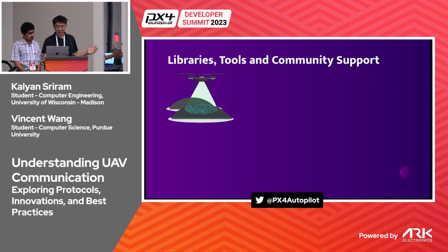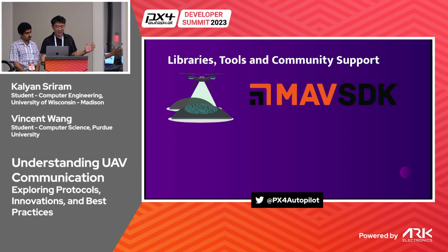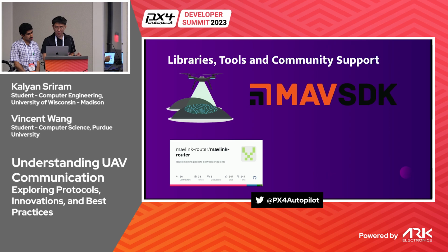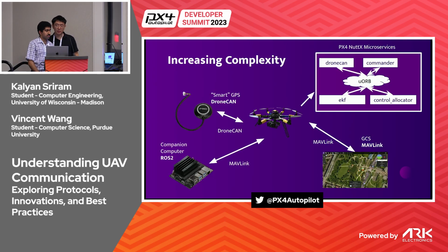The community also introduced solutions to make MAVLink easier to use. First with the DroneKit SDK, which abstracts some of MAVLink's message exchanges into methods, and now with MAVSDK, which provides high-level interfaces in most languages for all major MAVLink microservices and remains the current standard high-level library for MAVLink. Other tools like MAVLink Router also sprang into existence to better manage multiple drones on the same network. MAVLink Router and similar tools allow users to split or combine MAVLink streams from or to multiple sources and destinations for easier handling. We're in a good position now.